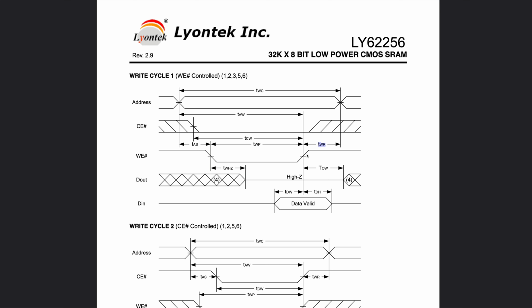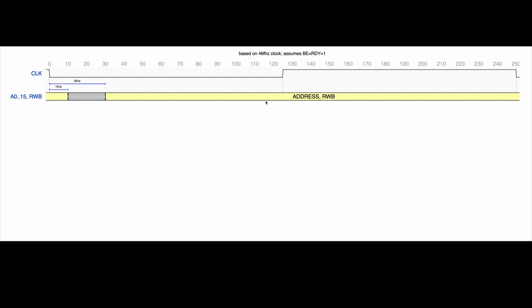So we have to control the order of this pulse here. And the way to do that is with the clock. And so what we're going to do is we're going to say, well, we only want to be writing when the clock is high. This way we're going to have a rising pulse here when the clock is falling. And then it's going to give us 10 nanoseconds before the address starts changing. So let me add it to the diagram here.